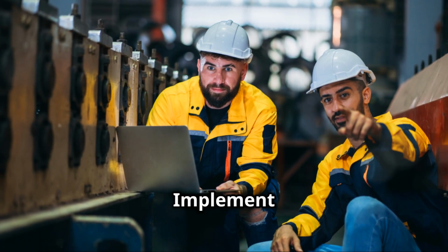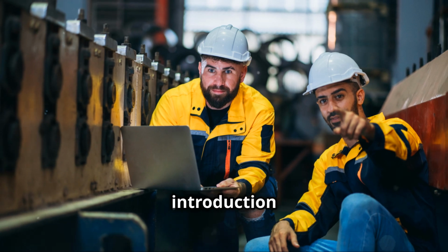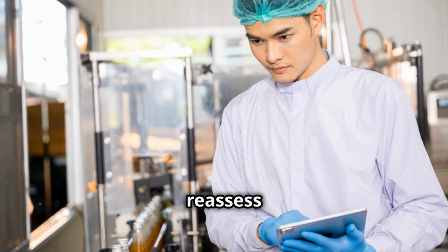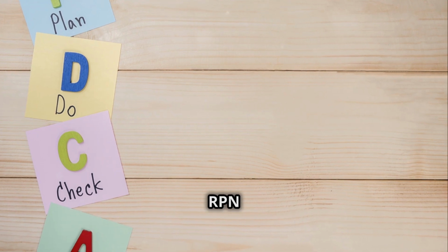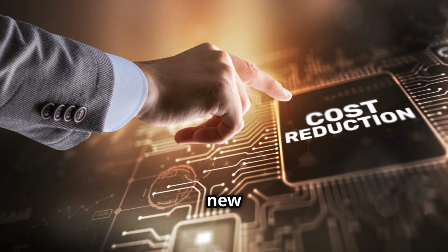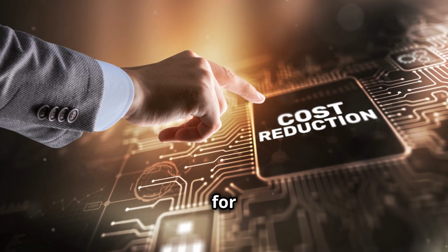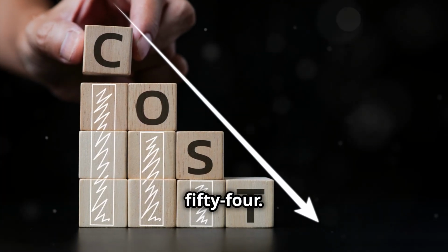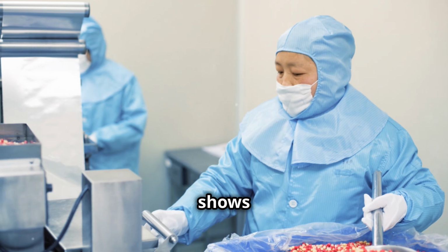Step 6. Implement corrective actions. After the introduction of torque sensors, real-time alerts, and improved training, reassess the process. The new RPN for loose bolts reduces to 90. The new RPN for over-tightened bolts reduces to 54. This shows a significant reduction in risk.